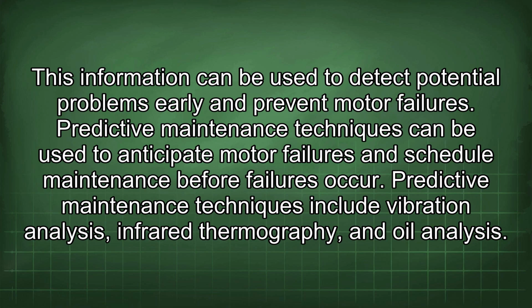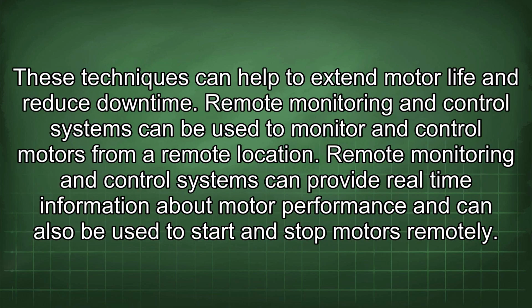Predictive maintenance techniques can be used to anticipate motor failures and schedule maintenance before failures occur. Predictive maintenance techniques include vibration analysis, infrared thermography, and oil analysis. These techniques can help to extend motor life and reduce downtime.